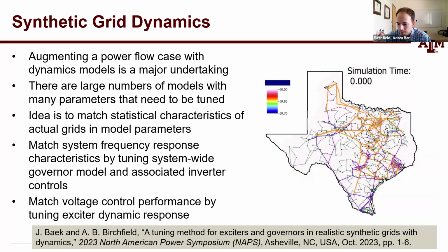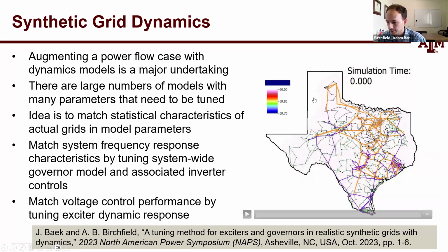We've got this paper that is mentioned right here. We also have another one that just recently got published that I can share as well. And we can create this. We have this out there for the Texas 2000 bus case, and we've even got some updated ones with more wind and solar models. But I've got a video here I can show that basically is going to show a frequency response plot for this synthetic grid, where we're going to be opening up a generator in the Gulf Coast region and watching the frequency response.